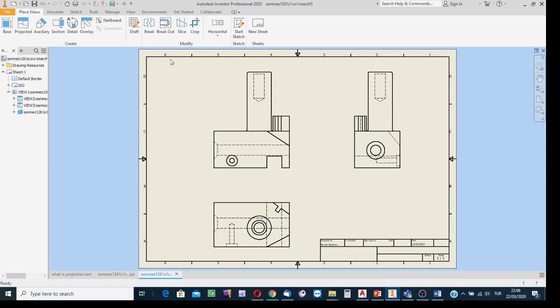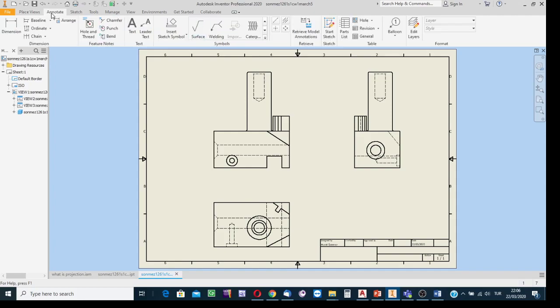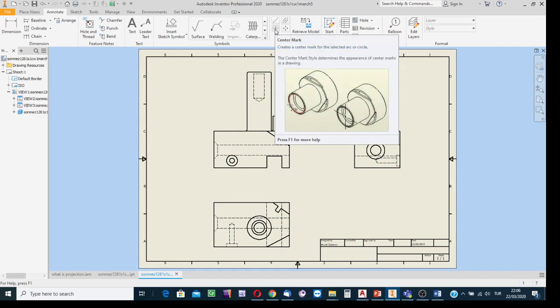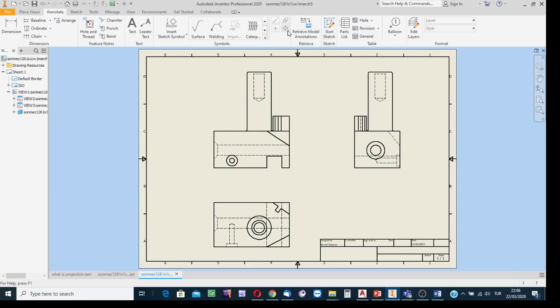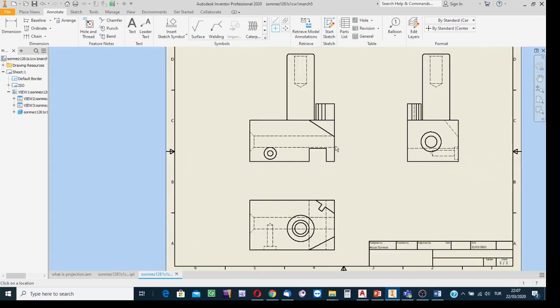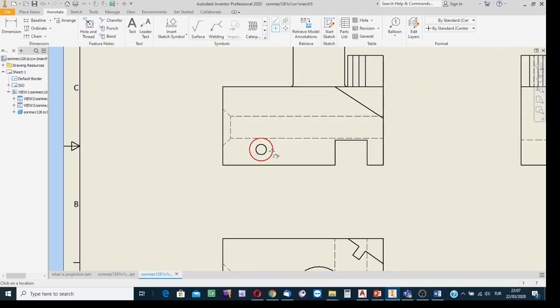Well, show the symmetry axis in Inventor. In the annotation tab, along the annotation ribbon, this is the facility to create the horizontal vertical axis. This is the facility to create the longitudinal axis. Click on this button to start the axis creation process, and then indicate the outer circle, or outmost circle, on the projection.